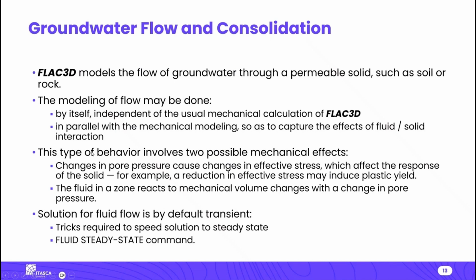So what that means is that if you change the pore pressure, you change the effective stress, which of course can cause more yield, but can also cause movement, as I was just showing. So that's one way. The pore pressure affects the mechanical. The mechanical can also affect the pore pressure. So if you change the volume of the pore spaces, you can change the pore pressure. Imagine if you're squeezing a pore space, the pore pressure will go up. Or if you're relaxing a pore space, the pore pressure will go down. So there's a two-way coupling here. Pore pressures affect the mechanical, and the mechanical can affect the pore pressures.